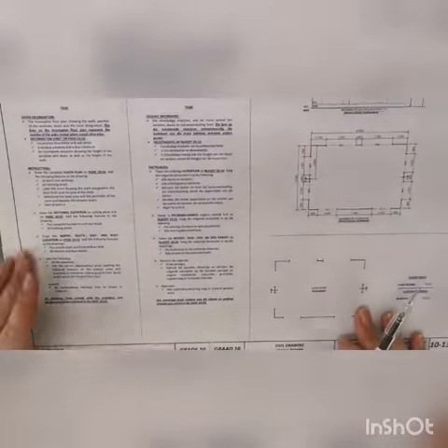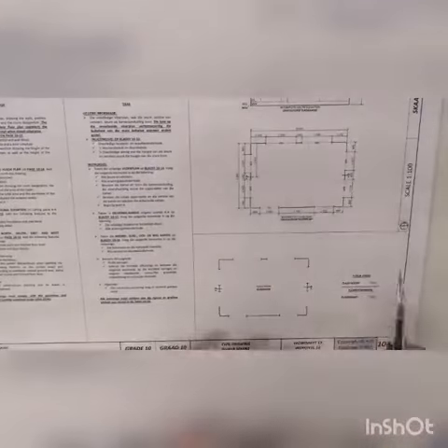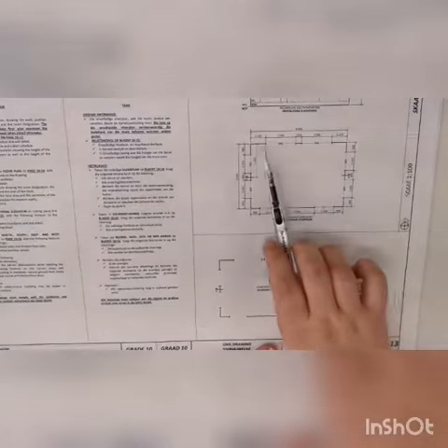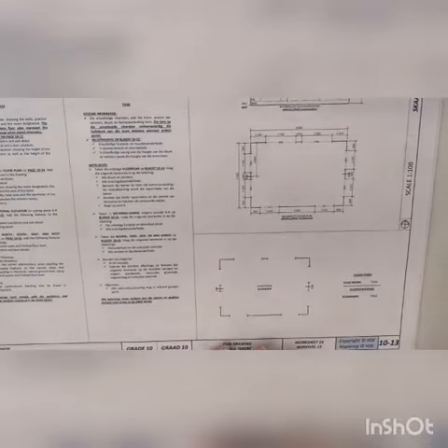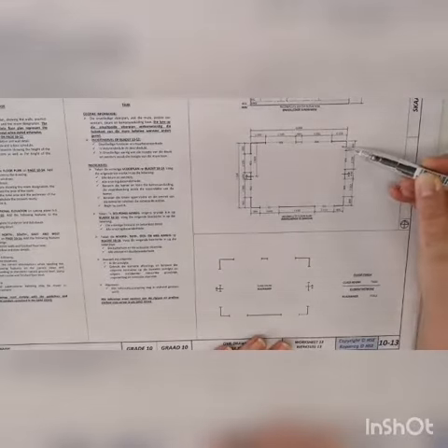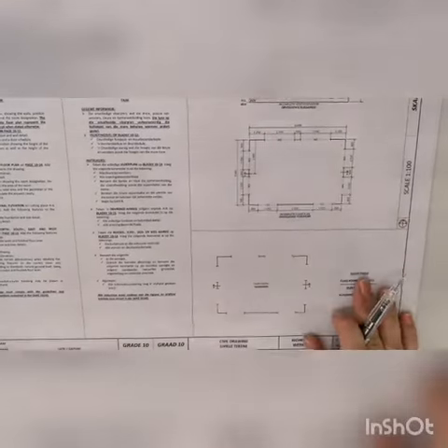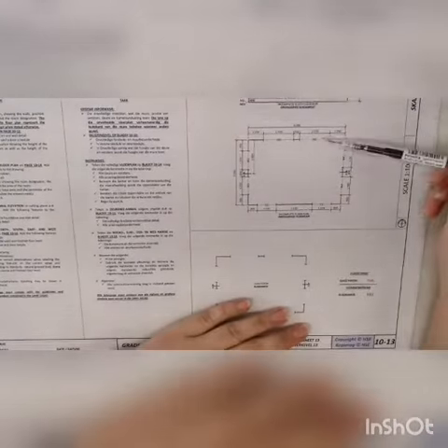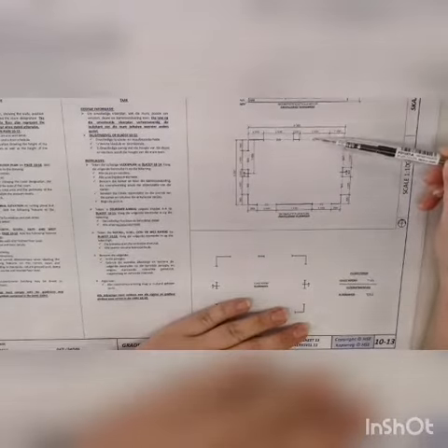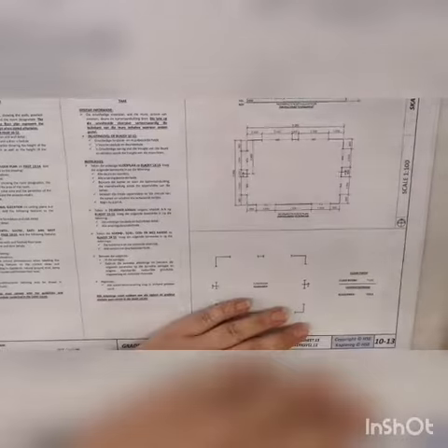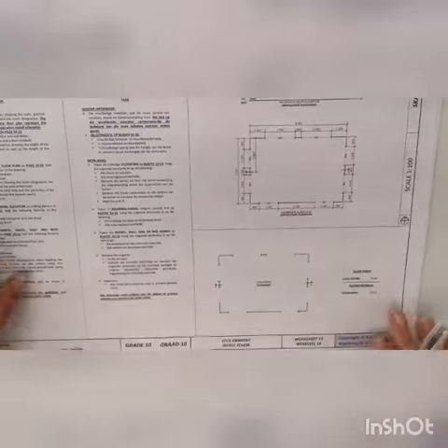So that's quite important. When you are given an incomplete floor plan, you are given one line. But when we draw, we have to draw the thickness of a wall. So we don't take the thickness of the wall outside, we take the thickness of the wall inside. So here's our incomplete floor plan, showing designations: W's are windows, D's are doors. Alright?